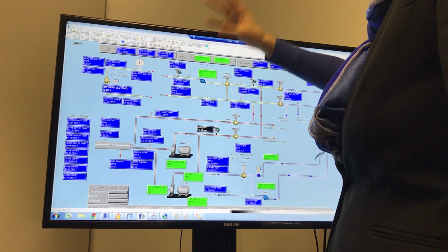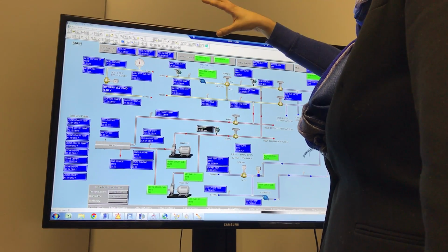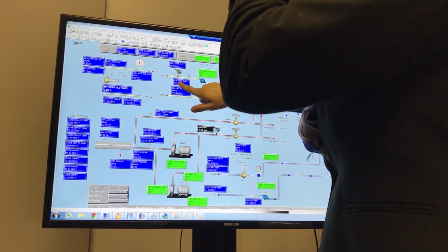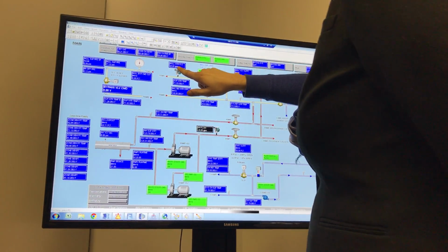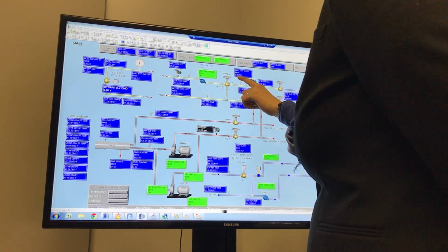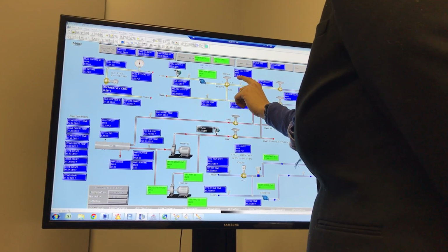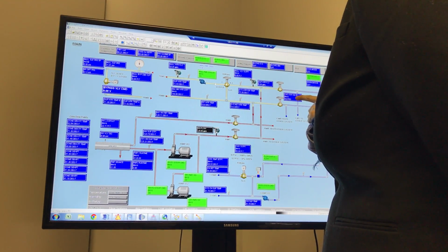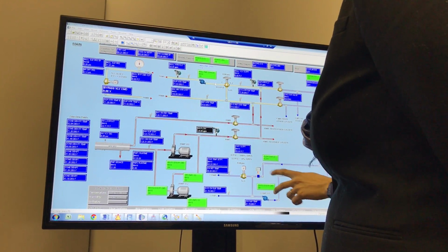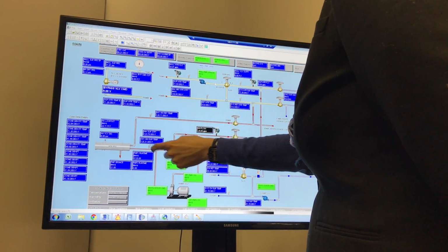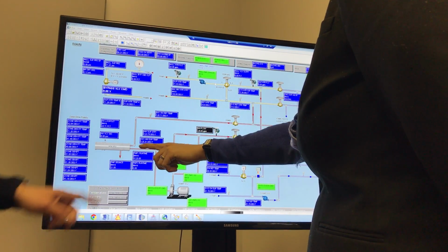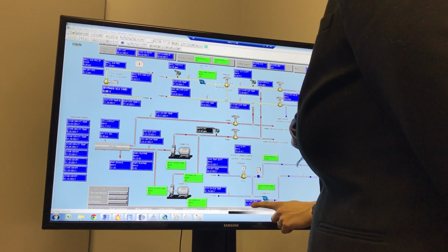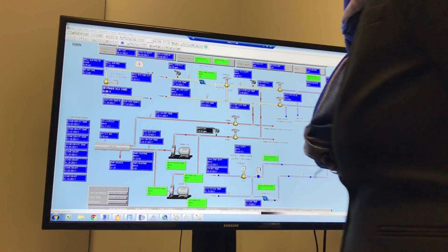Yes, you go from here to here. First you will ask, is my pump on? Do I get the correct supply water temperature? Do I have flow? Okay, everything is fine. What's the status of this? Is it really demanding cooling? Then you come here: is my valve stuck? No, it looks fine. Are my pumps on? Is the temperature coming from my basement okay? 125? Okay. 42 might also be some from the campus itself. Okay.